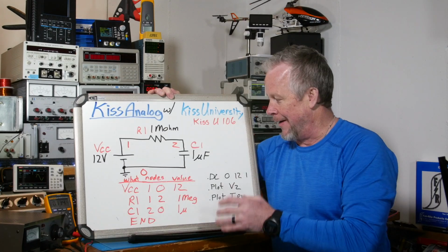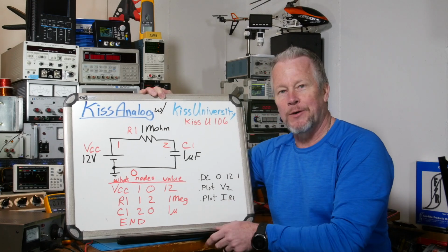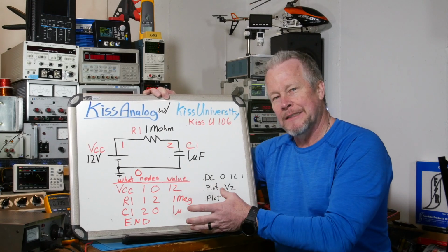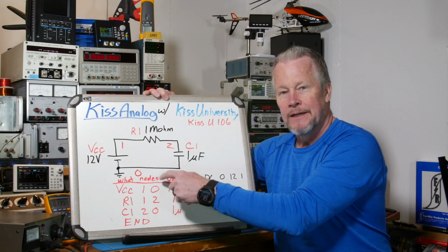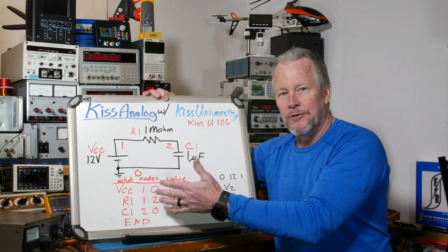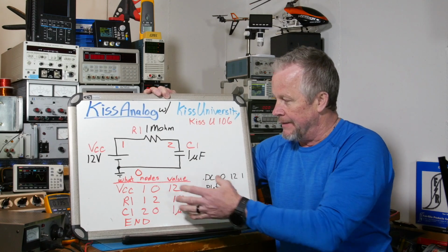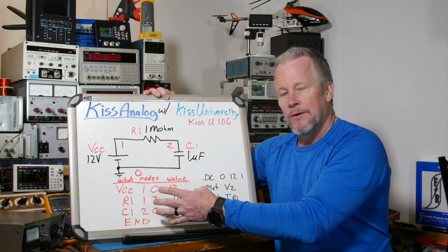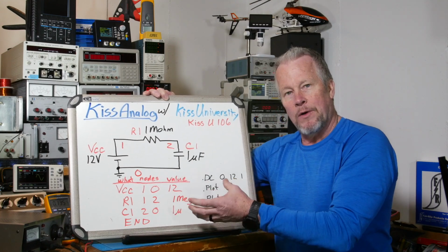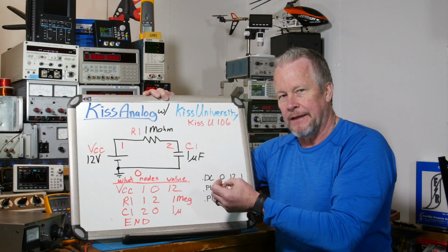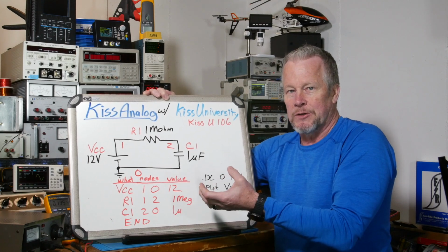All right, so I just added a few things right here. What I wanted to explain is that once you've described your schematic, writing this net list or this nodal list, then that's your schematic written down in some kind of list format, and the SPICE program is going to suck that in, and then it knows what your schematic looks like.